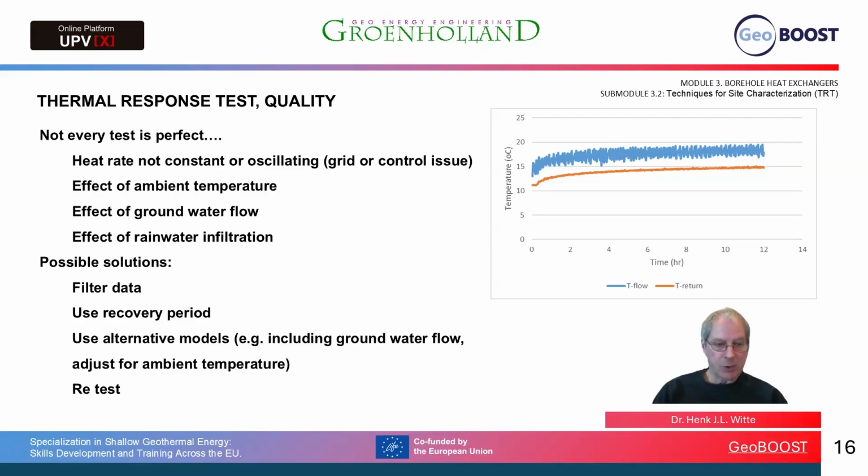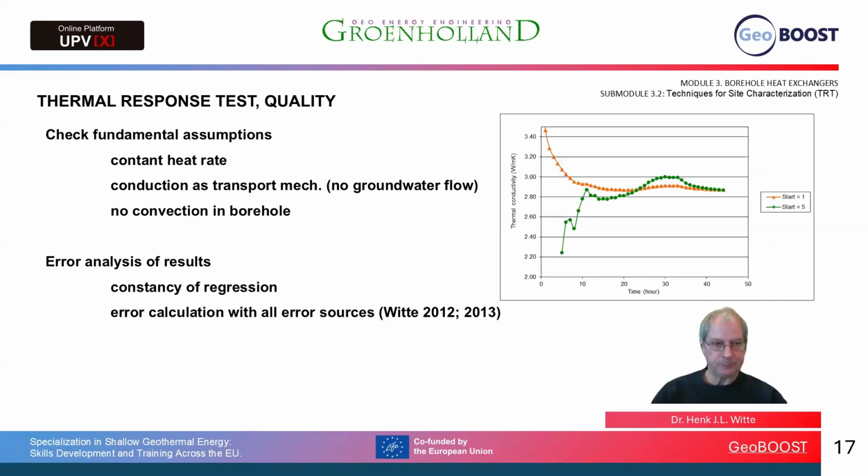We can use different, alternative models, for instance, models including groundwater flow or adjusting for ambient temperature to get a better estimate of the thermal conductivity, taking into account other processes that occur. And of course, it is always possible to retest. That means that you have to do the evaluation of the test data before you remove your thermal response test away from the location. And you can wait for a couple of hours or a couple of days and do a further new test on the same borehole.